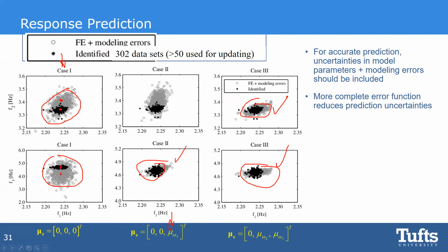We are doing model updating, but a lot of times when we have a complex structure, your data tells you something. For example, here you see my predictions are gray. I want my F2 to come down. If I tune my F2 to come down, my F3 will also come down, but that's bad. You see, they are pulling in different directions.